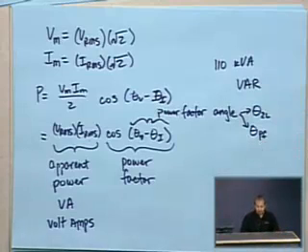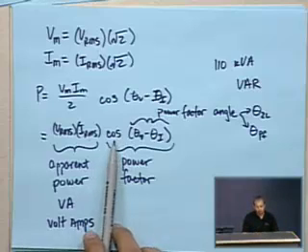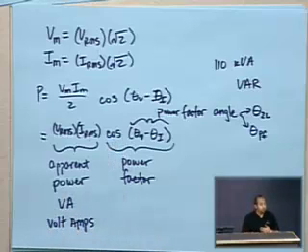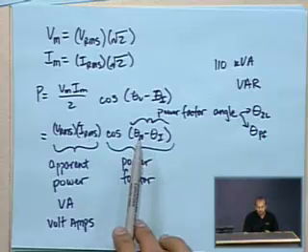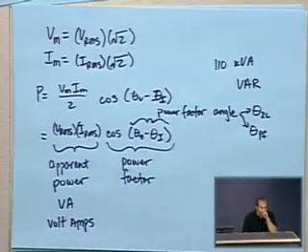And so if you ever know the power factor angle, you can calculate what the power factor is given the cosine. You can perform an inverse cosine on the power factor itself to get the power factor angle, which gives you the difference between the voltage and the current. You have these relationships, and you can start messing around with them as you see fit, or as you see necessary, I guess.